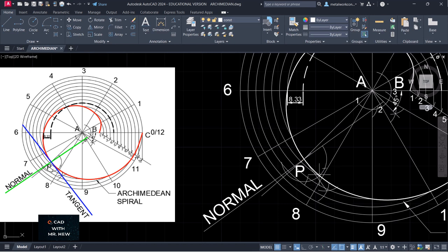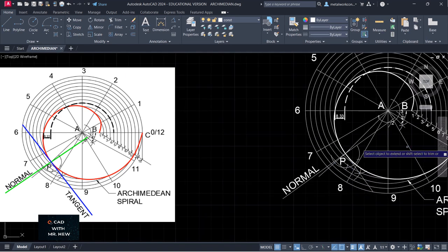Intersection, press enter. Right? So what we're gonna do now is extend the line in both directions. We're gonna select it down, extend it down here first. So we're gonna type extend. EX is the shortcut for extend. I'm gonna click this line, this line, this. Make it smaller.